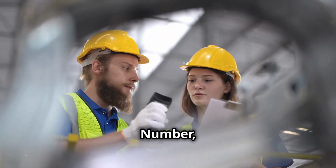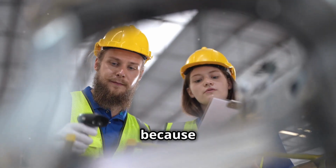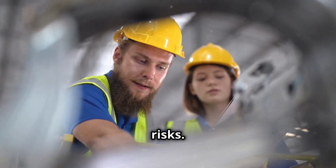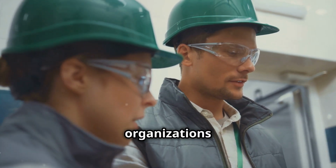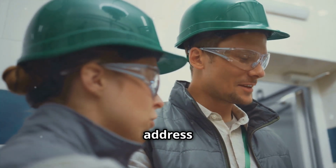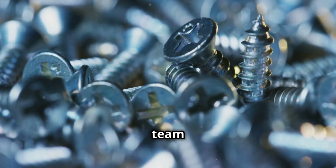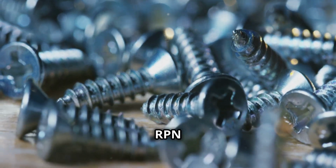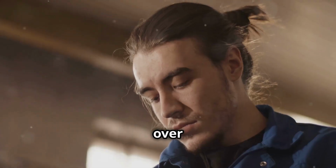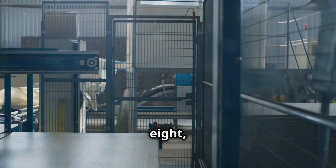The risk priority number, or RPN, is essential in PFMEA because it helps prioritize risks. By focusing on the highest RPN values, organizations can allocate resources to address the most critical issues first. In the example above, the team prioritized addressing loose bolts with an RPN of 180 over over-tightened bolts, which had an RPN of 108, due to the higher safety risk.